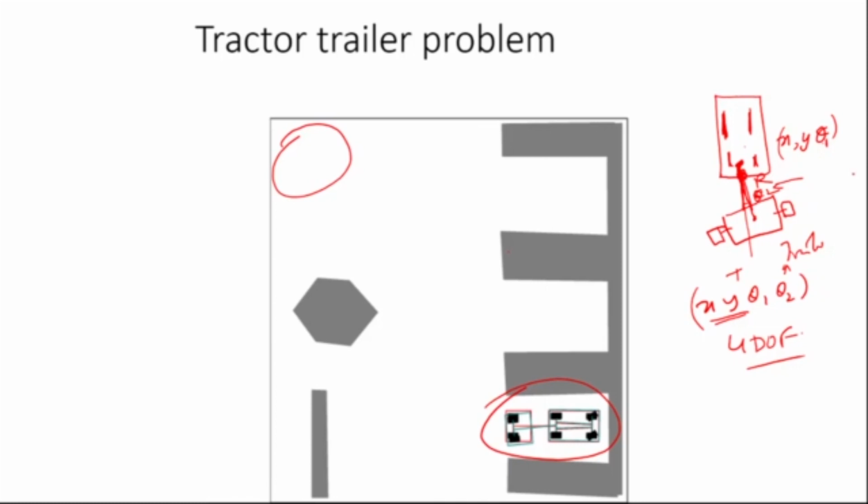So what we looked at today is essentially the question of controllability. That is, when we have a system subjected to non-holonomic constraints like this, how do we ensure that, first of all, the system is fully controllable? If it is fully controllable, then how do you build algorithms that will take it from some point to some other point and enable it to park? And we can do that only by using controllability algebra.